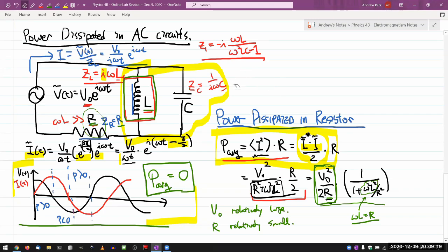If you imagine this going to high frequency, so that the impedance of the inductor is very high and the impedance of the capacitor is very low, then if you work out all the math, G1 should go like 1 over i omega C, again before it completely goes to 0. This quantity has a very special property.